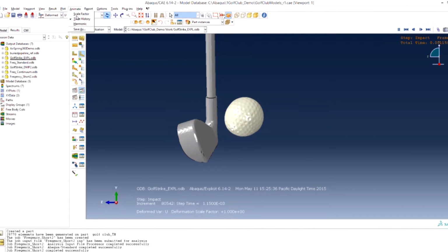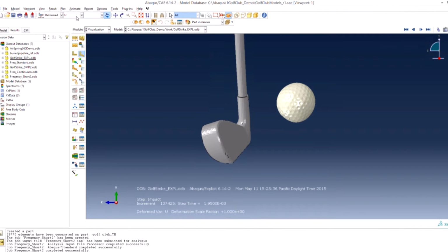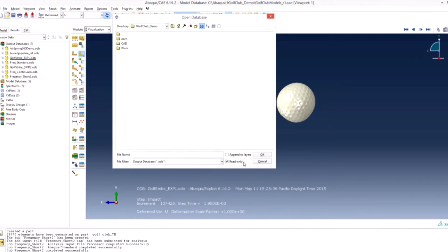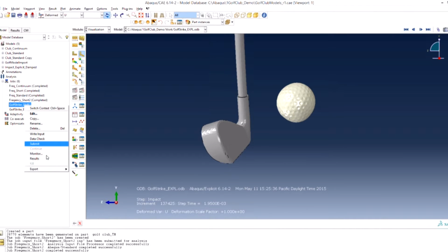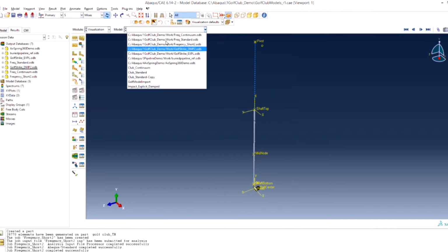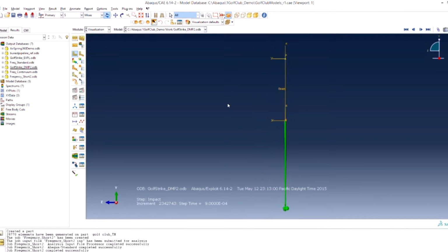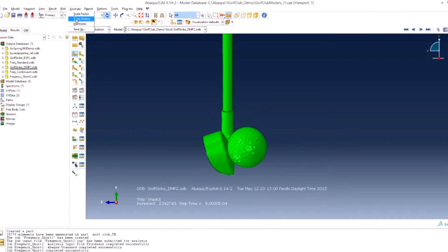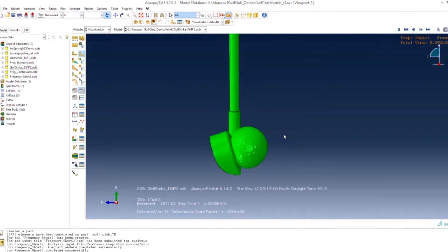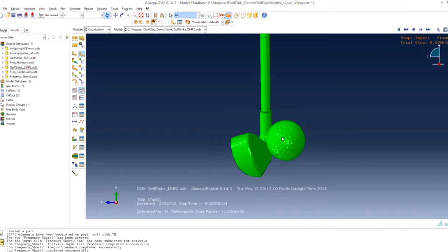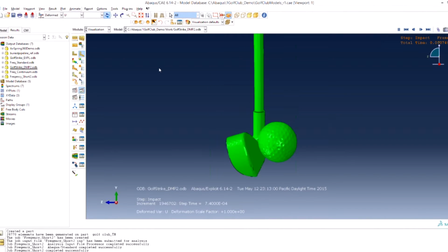One of the trade-offs of material damping is that it takes significantly longer to run an analysis. So one of the things I did here was to run this analysis for a shorter time with material damping. And so maybe this one will run somewhere on the order of 10 hours. But you get some nice payoffs for that, which is when we animate this shock wave, which travels back and forth once, and basically that ringing has almost died off by the end of that shock wave.